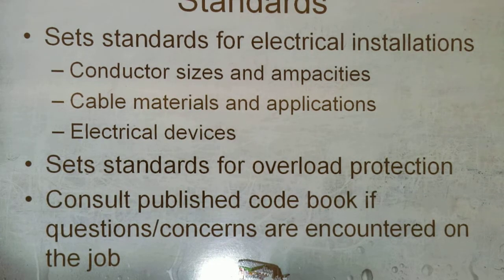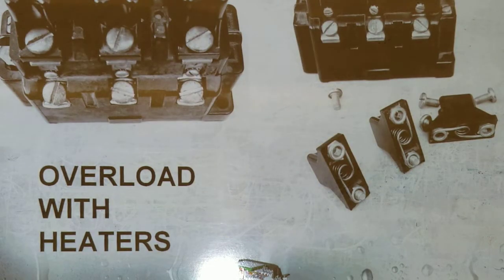Okay, so, remember me telling you this? National Electrical Code is in charge of sizing those overloads. These are heaters. Overloads with heaters. So the National Electrical Code is the one who's gonna determine what size heaters go on what motor.